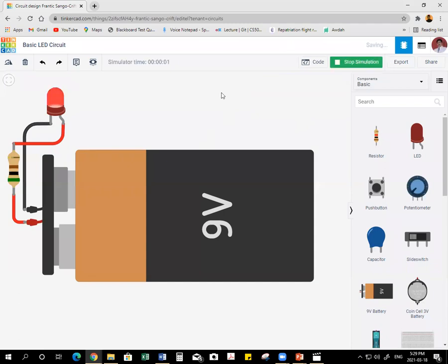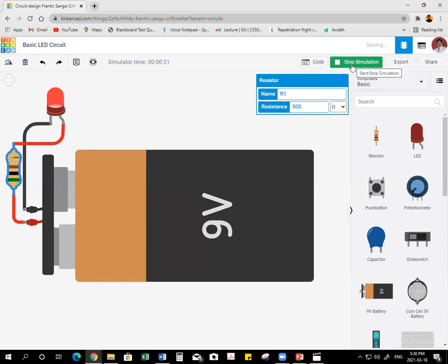Good, alhamdulillah. So we have a better appearance now. Now the LED is working with a resistance value of 500 ohms. Step by step, if you want to see the exact value where it gets 20 milliamps, you can do that later in your simulation. So this is the basic circuit I am showing here.